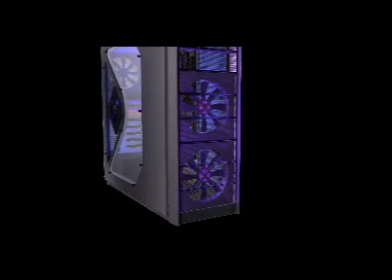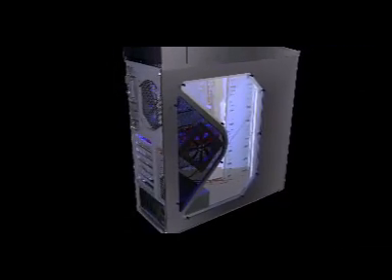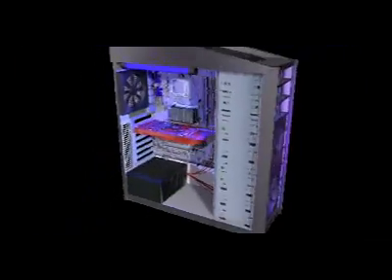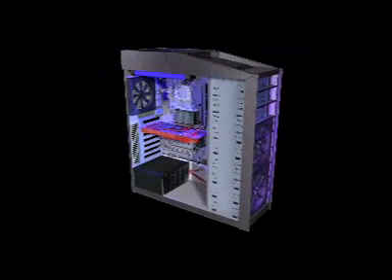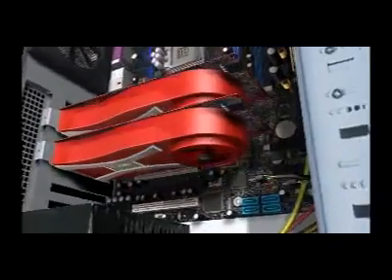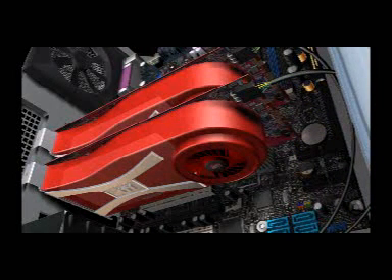Once you have the certified components, building a high-end CrossFire machine is fairly straightforward, though resellers want to keep a few things in mind. First, opt for a chassis with the technical considerations to house CrossFire. An enthusiast box with dual-slot graphics cards probably boasts a high-end processor and plenty of memory. Look for a case that ensures ample cooling and easy access to hardware. Keep in mind that each Radeon X1950 XTX card requires an auxiliary power connection. Again, it's important to use a CrossFire certified power supply with dual 6-pin power connectors and expansion to spare.